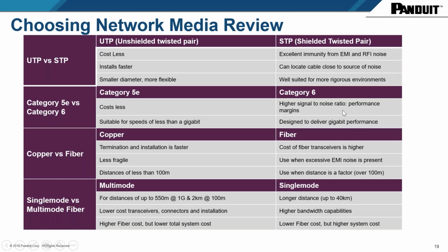This is where the standards are moving toward higher categories. When you use copper versus fiber, the distance is one of those concerns, and you could see here that anything less than 100 is copper, anything over is fiber. The EMI protection is higher for fiber. Why? Because fiber is not affected by power systems. So light and power, that's not a concern there.